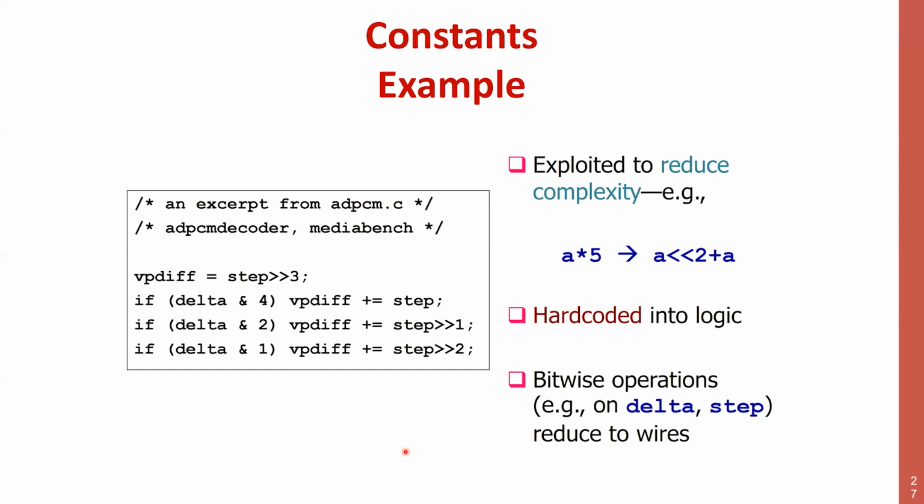We have seen the gains with constants. As soon as there are constants, hardware may become easier. There is one thing that has been exploited also in compilers, but these days that doesn't pay off very much because processors and hardware have become so cheap that processors all have multipliers and so on. But for instance, if I have to do a multiplication by 5, there is an operation, in compiler technology it was called, when it was done, strength reduction.